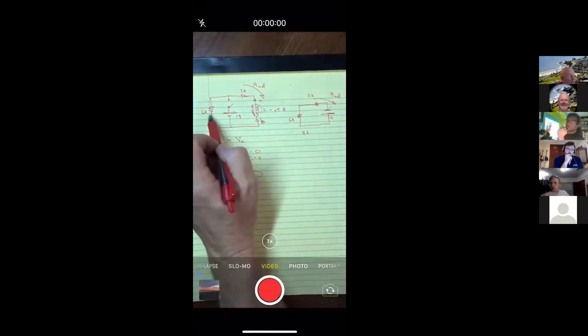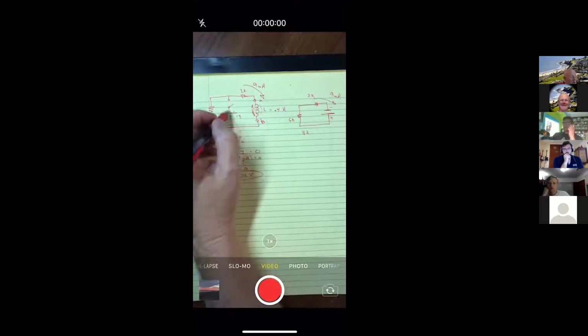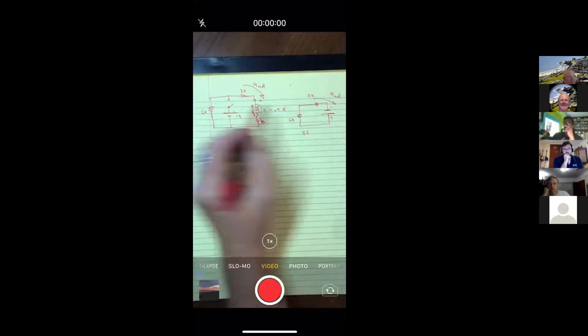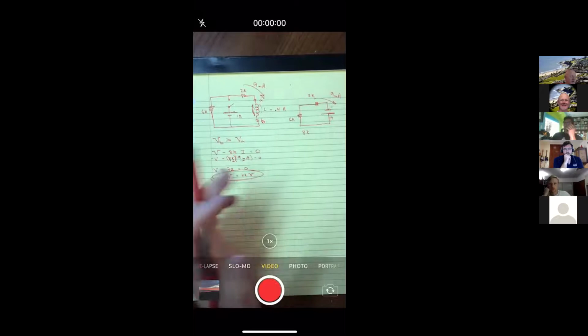And that's with the shunt resistor. So I probably design it this way so that when I'm running my battery and my motor, I'll leak a little current this way. Not that I want to leak the current that way, but so that I can shunt it this way so the voltage only jumps up to 72. If this resistor was greater, then this number would be greater. So there's a trade-off here.